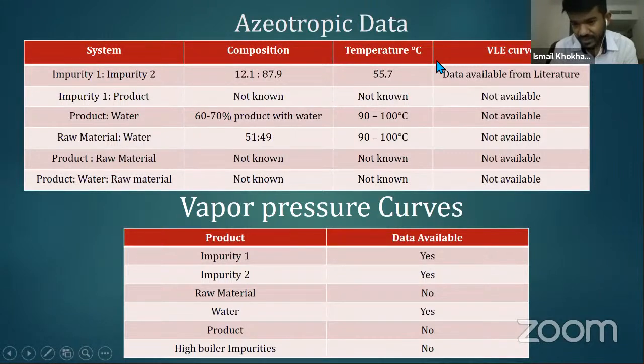Now, since the heating will start, in this capillary, the small tube over this bulb, you will see that vapor and liquid will start traveling because of the capillary action. Once it starts traveling, it will go up, and here at the top of this bulb there is a thermometer where you can measure the temperature of the vapor and liquid mixture. There is an arrangement at the top of the system where liquid gets collected on one side and vapor passes through the holes and goes to the condenser and condenses in this collector.